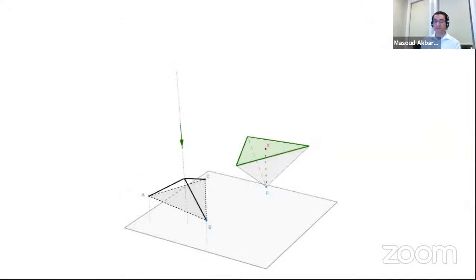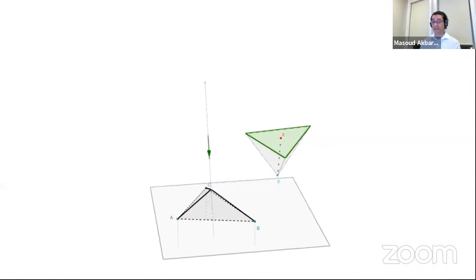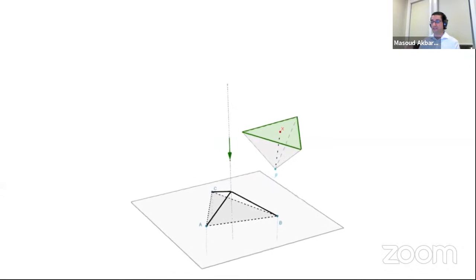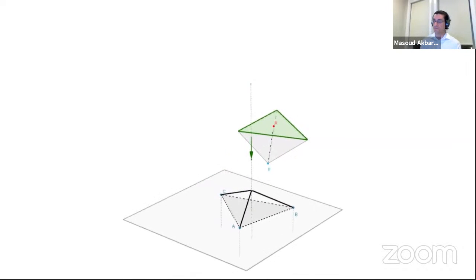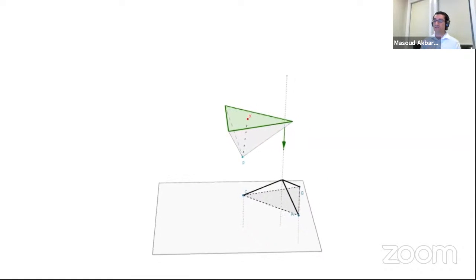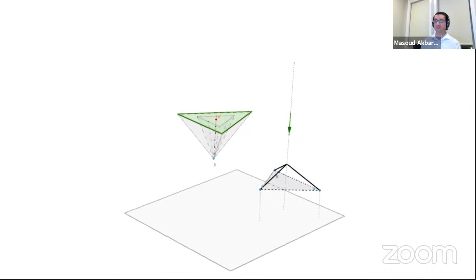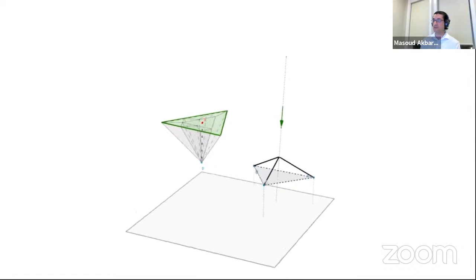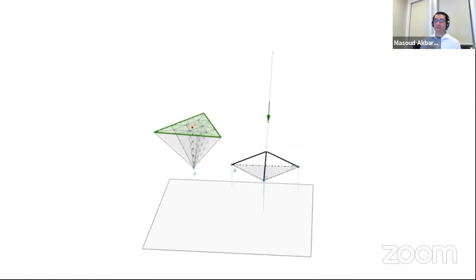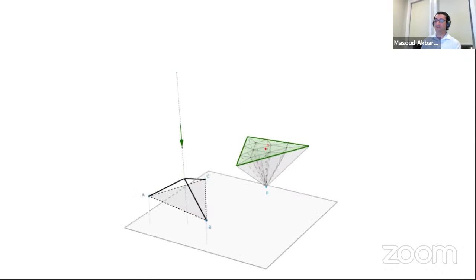So I'm going to show you a simple example of how 3D graphic statics can actually be used for form finding and rationalization of fabrication at the same time. So this is a single node, and the polyhedral tetrahedron that you see is actually its force distribution. And these two diagrams are constrained to each other. We are subdividing the force diagram, and as a result, you expect that the topology of the form will change